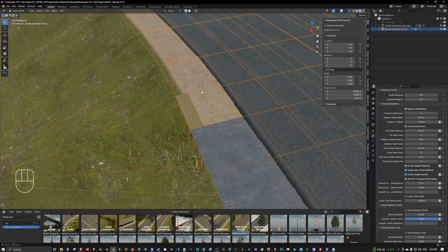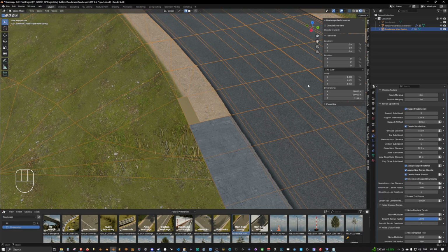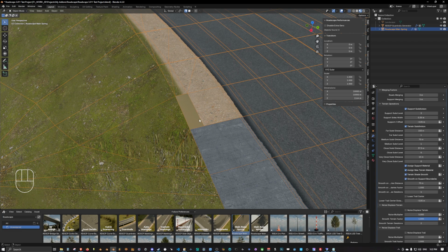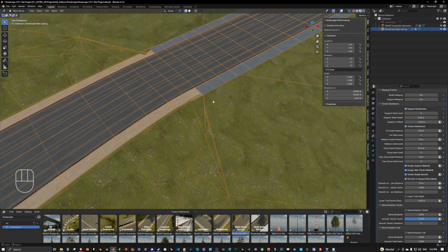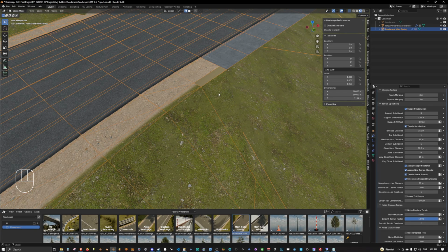It's just that the factor and the length of the curve onto which the generation of these faces is based is mixed and inverted on some of these faces, and so the scaling and rotation applied to the procedural unwrapping of these faces is inverted. So they are unwrapped, but the scaling and rotation is messed up. I haven't found a way to fix this yet, so this is one of the limitations of 3.1.